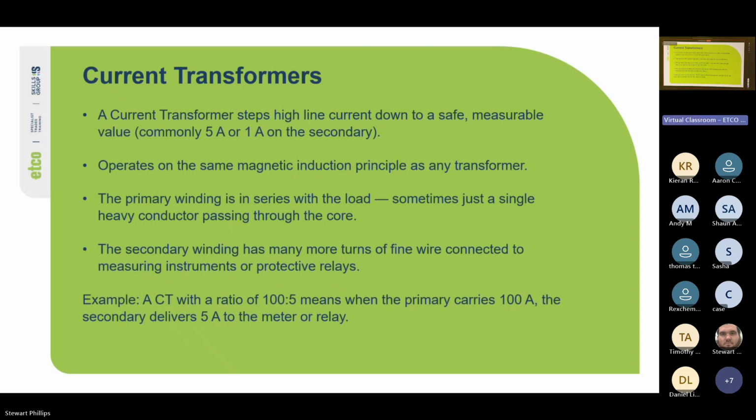There's all kinds of things. I've seen guys use a CT to turn on a laundry fan when the current flowing through the conductor to the power point of the washing machine reached over a certain value. So there are all kinds of different applications for a current transformer.